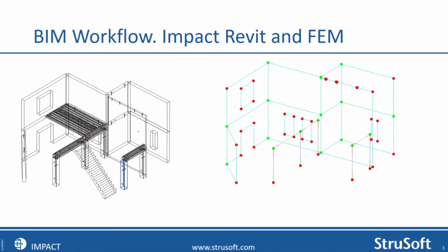so we're sure that the walls like here intersect in the right points, that we don't have two different planes not meeting each other. This is important if you're going to do structural analysis in a finite element software. It must be correctly connected. So this is important stuff, but it's easy to do. Revit has amazing tools for it now. It didn't have 2 years ago. We made our own plugin to make it even easier. And we have videos on YouTube showing that if you spend 10 minutes on this, you will be able to do it.